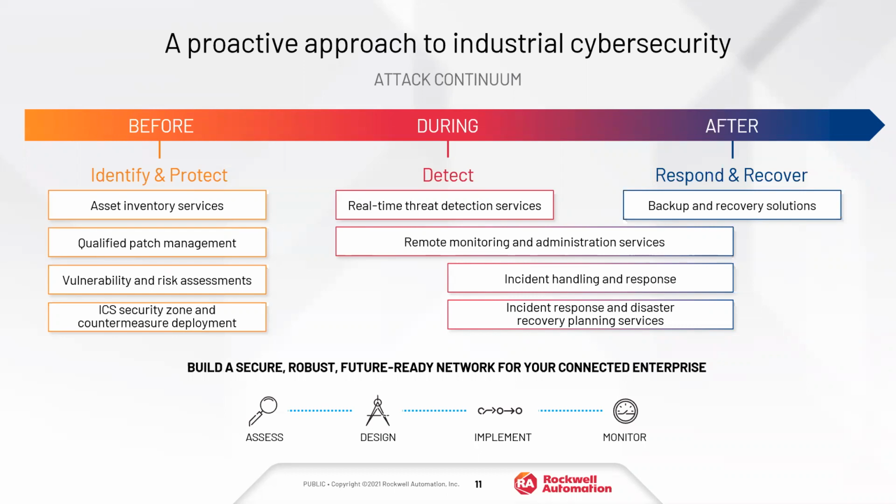So again, that's typically what we're looking at before an attack happens. During an attack, what you want to be able to do is detect that something is happening. So your most critical piece here is if somebody is making changes to your control system, if there's that quote unquote rogue laptop, you want to be aware of it so that you can plan accordingly.